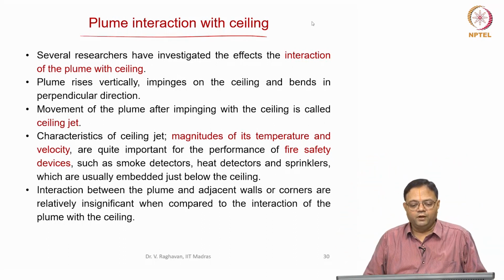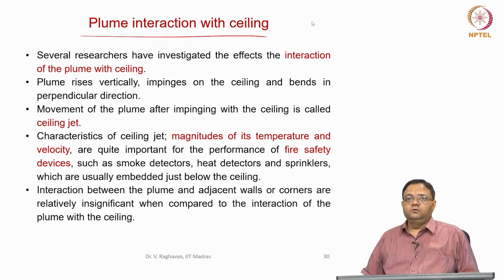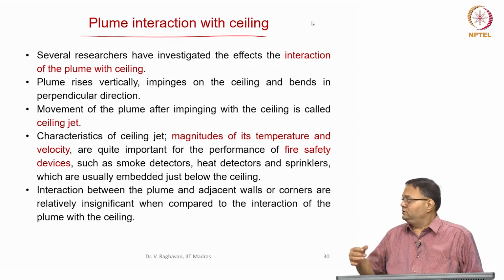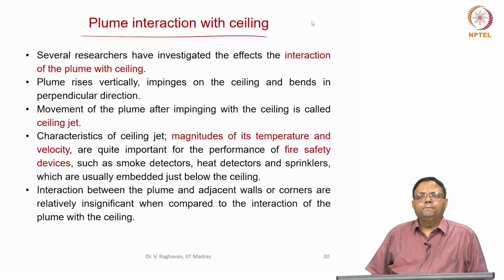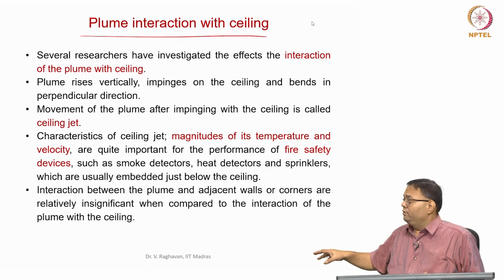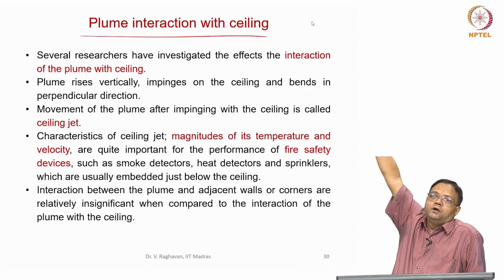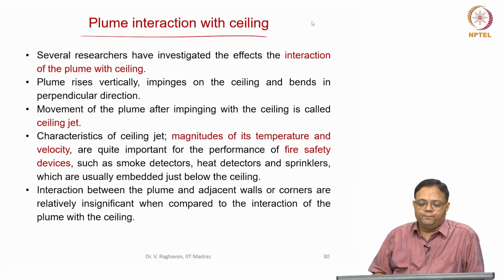ceiling basically. Now, if there is a fire in the corner, then the plume can straight away start interacting with the side walls. The interaction with the side walls will be there, plus as the plume goes and hits the ceiling, again the interaction of the plume with the ceiling will be there.